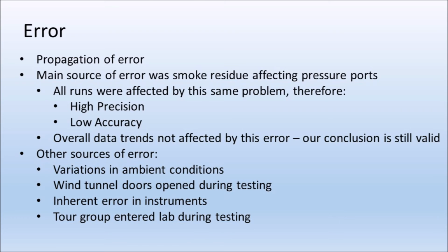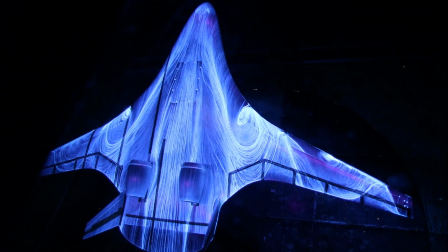from reaching our conclusions. We successfully confirmed that having a turbulent boundary layer in the flow over a cylinder significantly decreases drag. Using our trip strip of sandpaper, we were able to control where the boundary layer separates from the cylinder's trailing edge. Although our experimentation was focused on creating a turbulent boundary layer, the concept can be extended to any scenario where certain flow characteristics are undesirable.